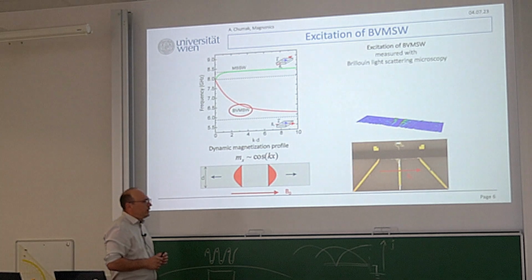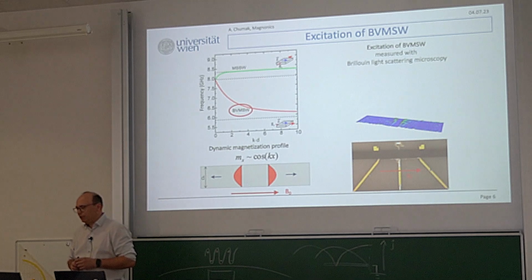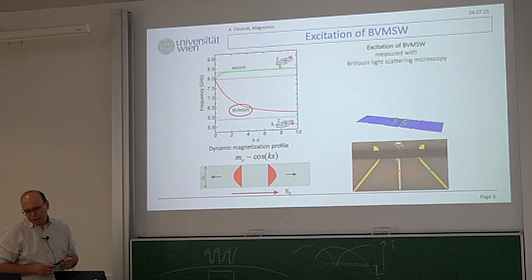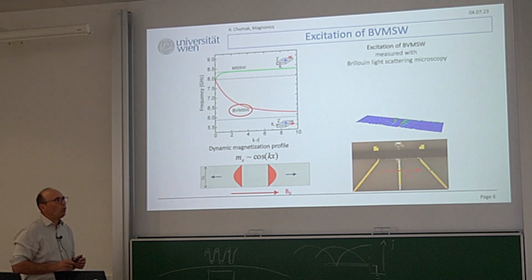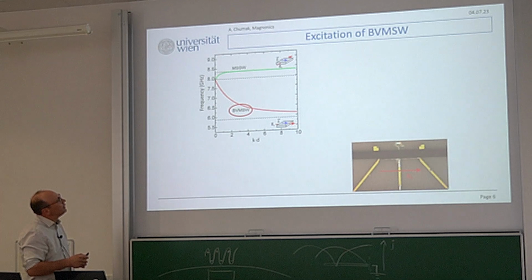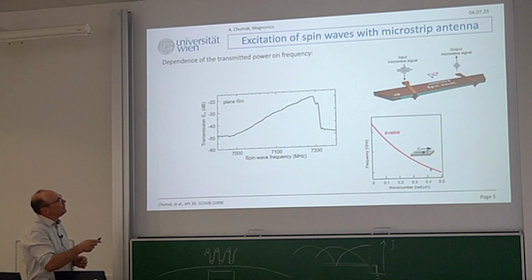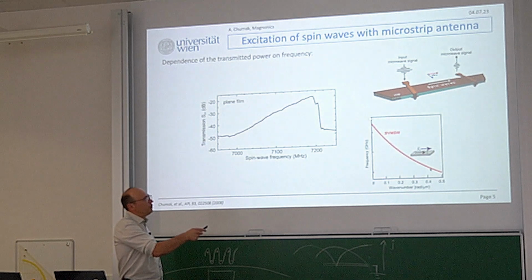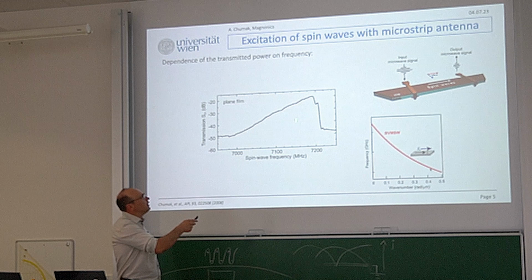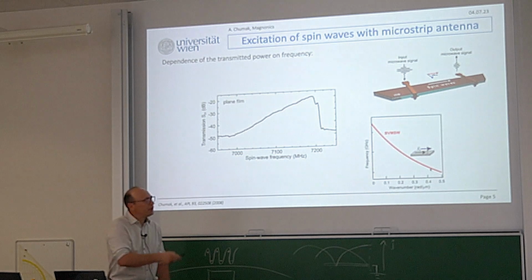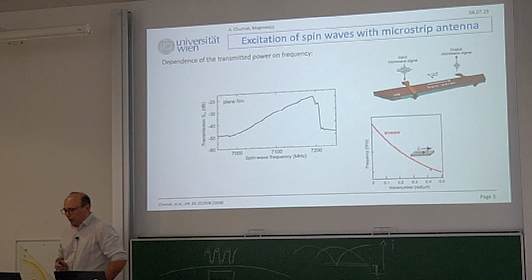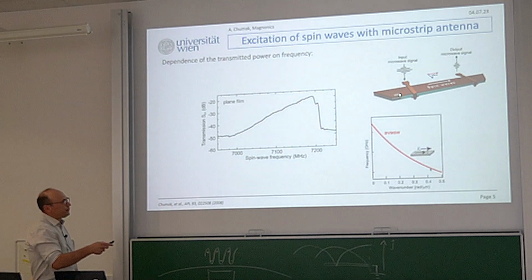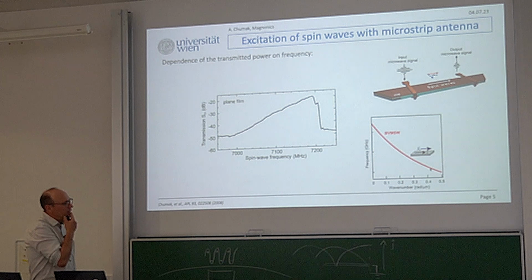Yeah, so usually higher width modes and higher thickness modes we don't really see here, or we see them but in the form of interference. So it might be that in the signal which you measure there is interference. So usually we see here these peaks associated with a higher width mode, because if you have a higher width mode, the dispersion goes from higher frequencies, and then you pretty often see some more peaks which are associated with a higher width mode. If it's about a thickness mode, then it's getting a bit